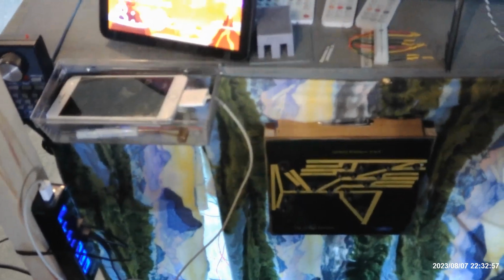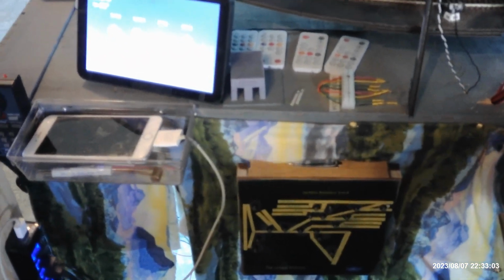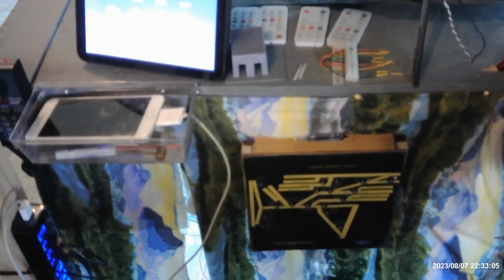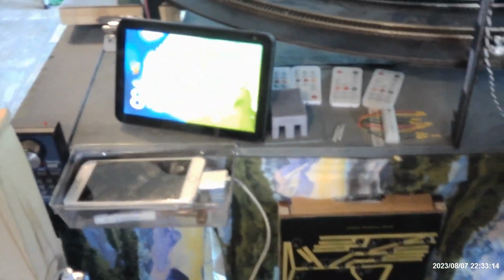I have 17 turnouts that I have Cobalt IP digitals on, and I needed 2 AIU-01s because the AIU-01s only have a capability of handling 14 devices. So I have 17, and I'm planning to put some more in later, so I'll have room for more.